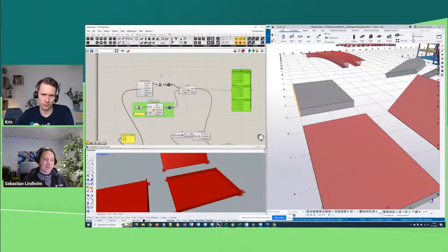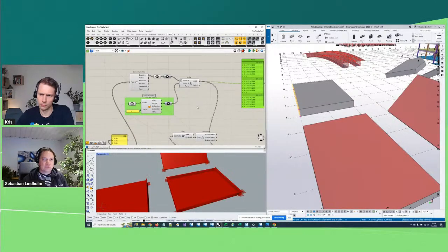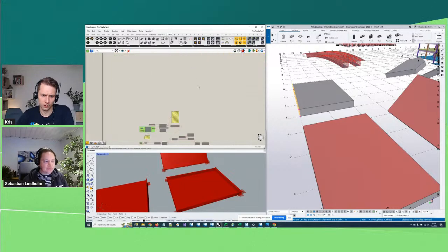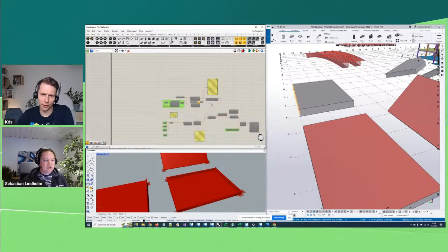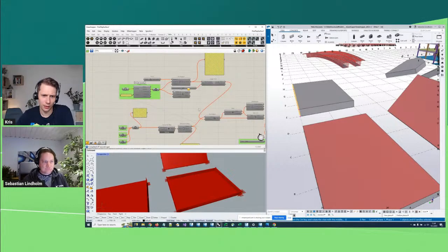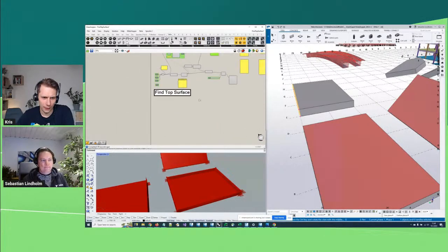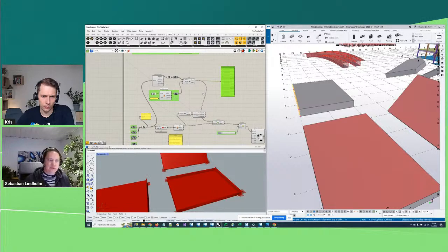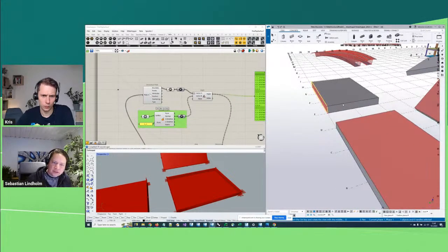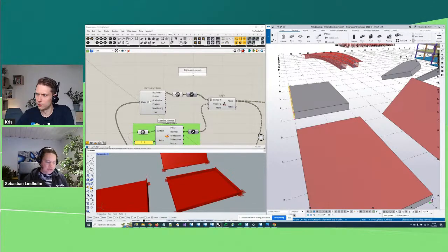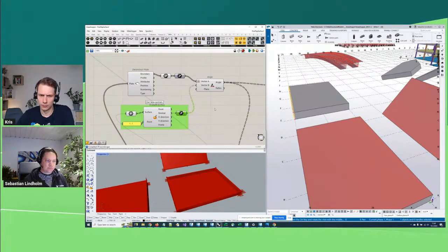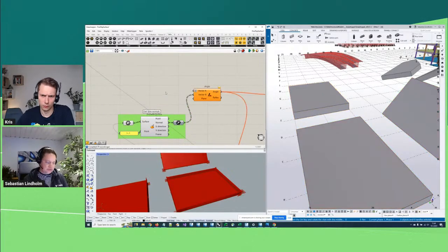And this time we want to get, let's see, what's the best way? I almost need to look at what I did last. Yeah, maybe finding perpendicular lines to the middle. That could be one. Yeah, there will be many different ways you can do it. But I think the one I arrived at is that what if we take all the surfaces that point roughly upwards, like their direction is anywhere above the XY plane. So we can do that by just getting these face normals and compare them against the Z direction.